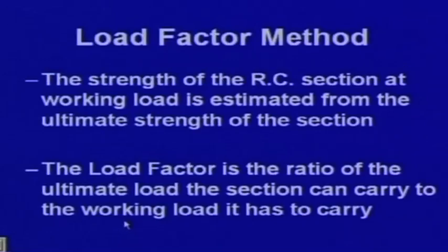So, one is coming from the resistance of that particular section, considering the ultimate strength, considering the nonlinear part of the stress strain curve of the concrete, and from there we get the load factor method, because concrete behaves in a nonlinear way due to creep and shrinkage. That is what governs the behavior of the concrete, and that is why it is worth considering the nonlinear part of the stress strain curve.